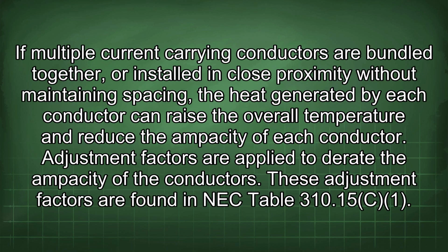310.15(B)(2). If multiple current-carrying conductors are bundled together or installed in close proximity without maintaining spacing, the heat generated by each conductor can raise the overall temperature and reduce the ampacity of each conductor. Adjustment factors are applied to derate the ampacity of the conductors. These adjustment factors are found in NEC Table 310.15(C).